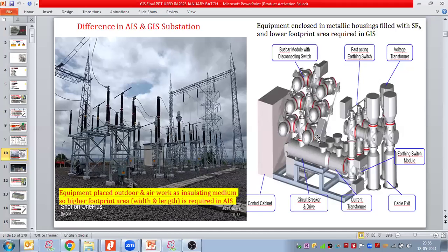And here we have the operating mechanisms. So this assembly represents the bus disconnectors, bus isolators. As you can see here, this is my bus isolator, as in the AIS type substations. And here we have a two bus bar scheme in this particular GIS photo. So bus 1 here, bus 2 here, and due to that we have two bus disconnectors, one here and one here. And then after the disconnectors, we have the circuit breaker module, breaker equipment here.